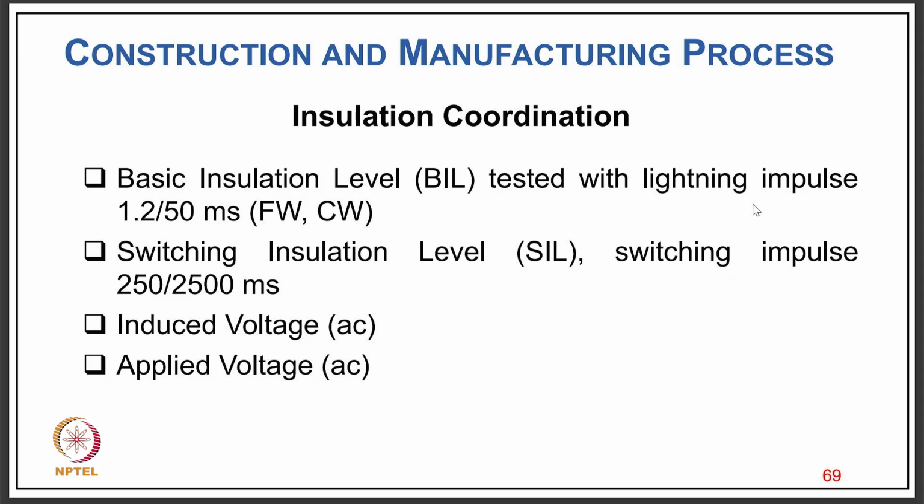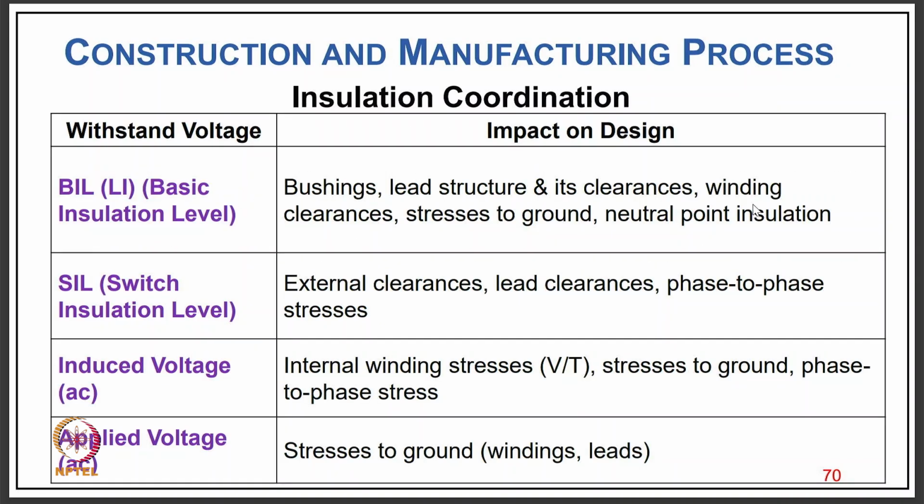And then of course we have the insulation coordination standard: basic insulation level tested with lightning impulse of 1.2/50 microsecond, the front wave and the chopped wave, and the switching insulation level with the switching pulse, and then the induced voltage, and then the applied voltage.